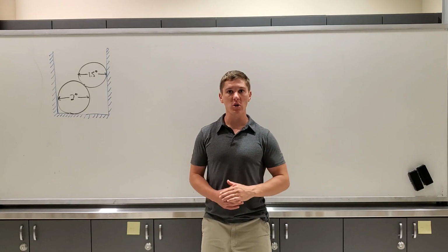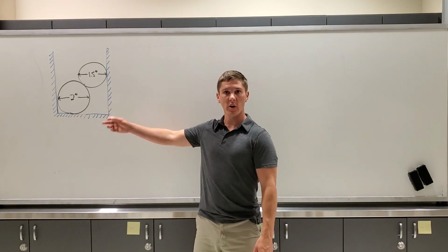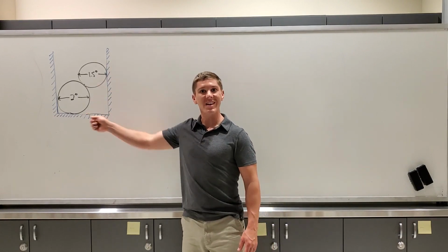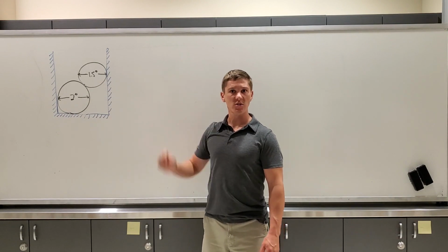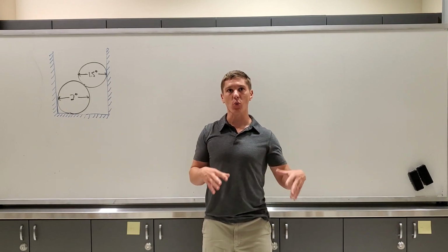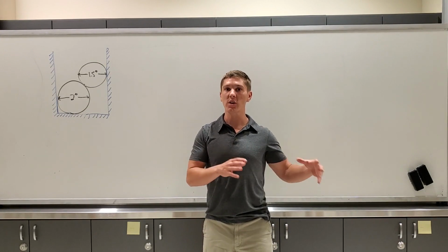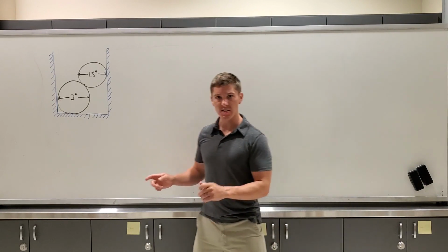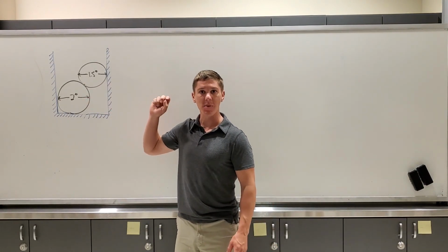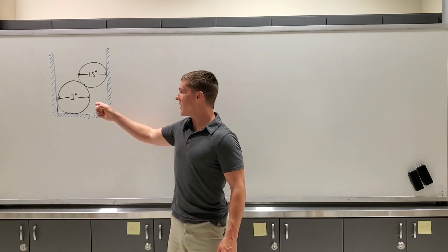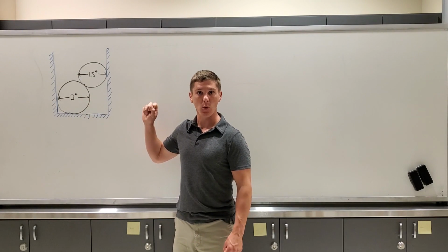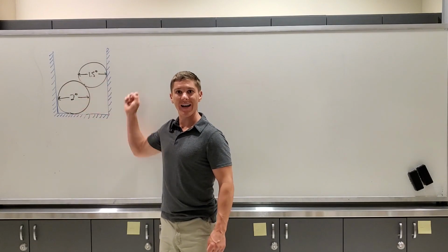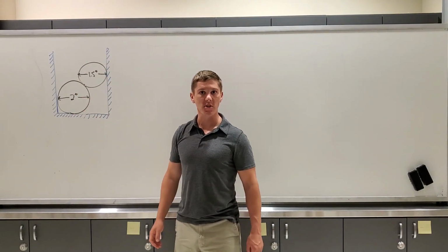How do we determine those equations of equilibrium for this kind of problem? Well, we're going to do it by drawing free body diagrams. In fact, we can draw up to 3 different free body diagrams for this problem. I want to talk about each of the 3 free body diagrams as we come up with them and how we can analyze this problem. The first free body diagram I'm going to draw is of the system of the two particles. If each individual particle is in equilibrium, then the system is also in equilibrium, and I can analyze the system as a whole.